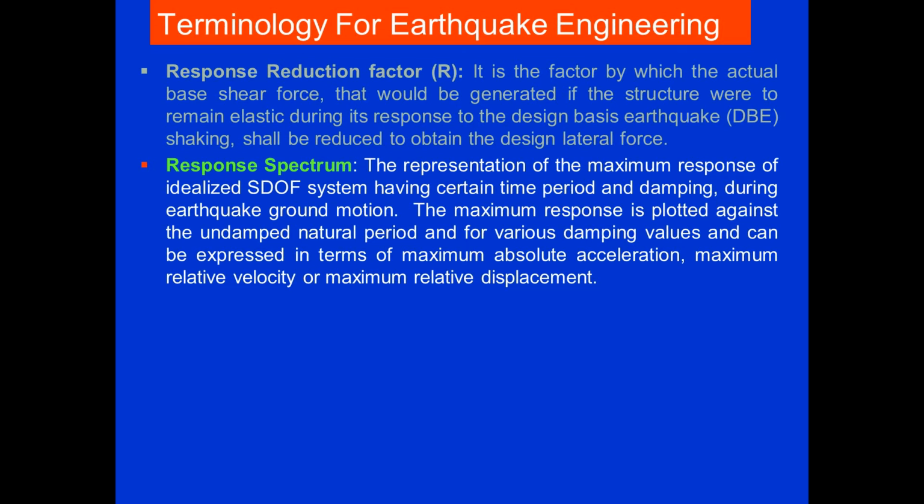So response spectrum is nothing but a representation of the maximum response of an idealized single degree of freedom system, SDOF, having a certain time period and damping, during earthquake ground motion. The maximum response is plotted against the undamped natural period for various damping values, and can be expressed in terms of maximum absolute acceleration.